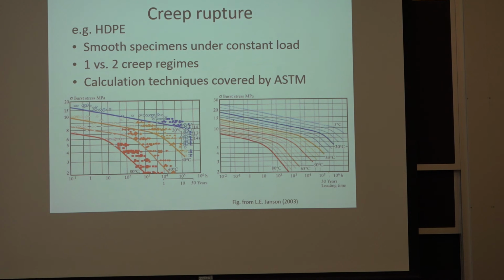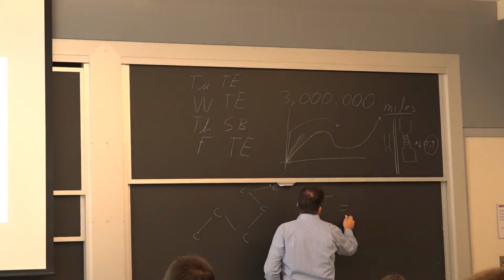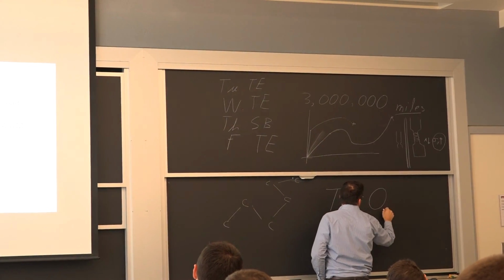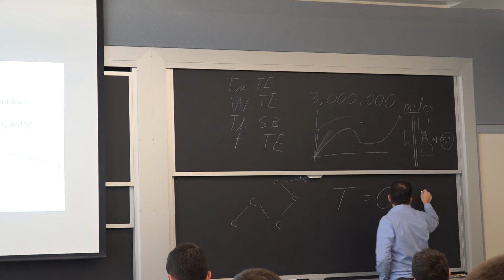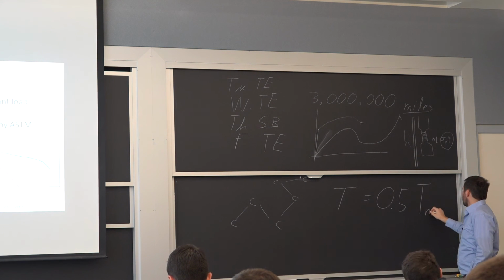So why does it creep? Somebody else, by the way. Why do plastics creep? There's a very, very simple answer. We're using them close to melting point. A lot of movement going on. So by basic principle, that's something I'd like you to remember. The temperature where you start to have creep is half the melting point.